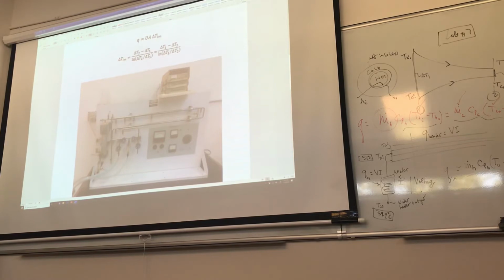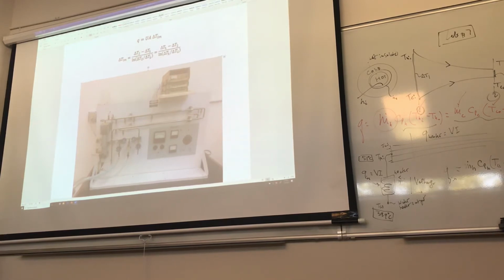Now, where does it exit? It comes in like that, and then comes in like this. Remember, this valve was closed, right? And this one will be open, so it's going to come out through here. So cold in, cold out. And again, the thermocouples are exactly the same thermocouples that we need to be reading, right? And you guys need to probably take a picture of that to just see where the thermocouples are.